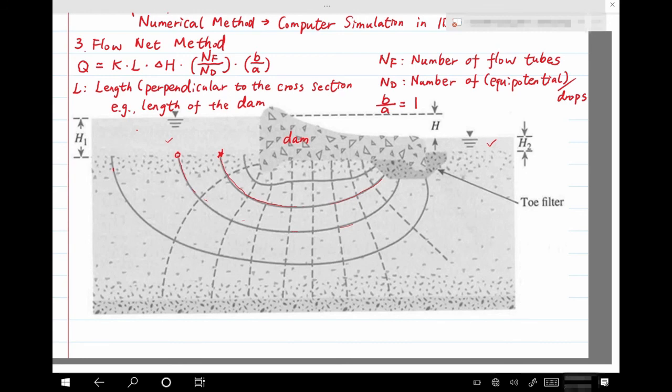Here, you can see different water levels on two sides of the concrete dam, and because of that, water is going to move from the left-hand side to the right-hand side. If we take a look at different points, for example, this point represented by a star, and the point represented by a circle, the water at these two points will move through the soil underneath the dam to the right-hand side.